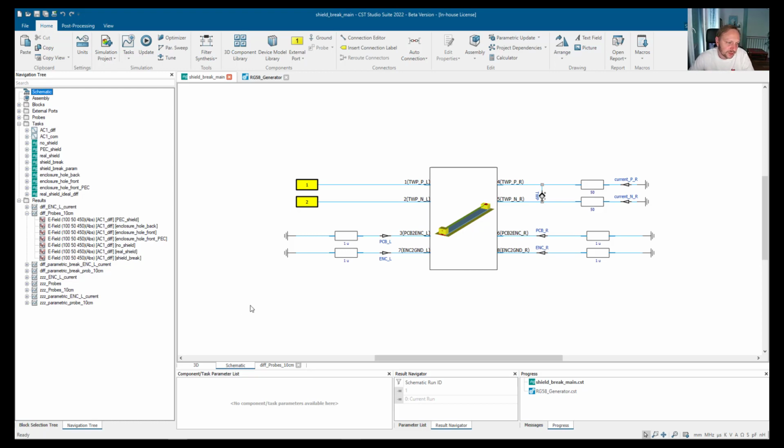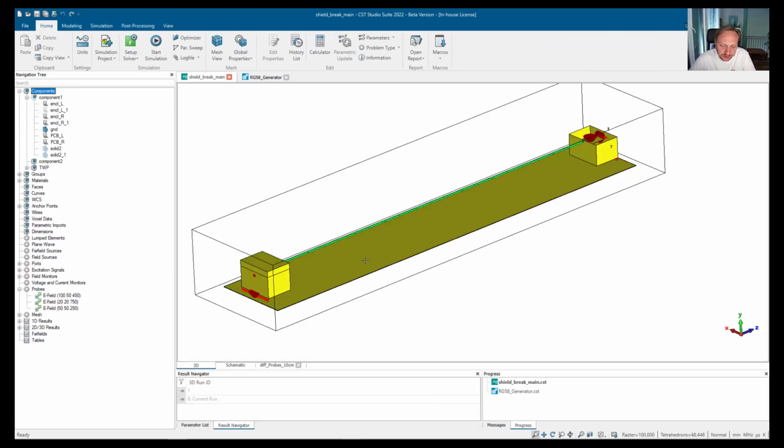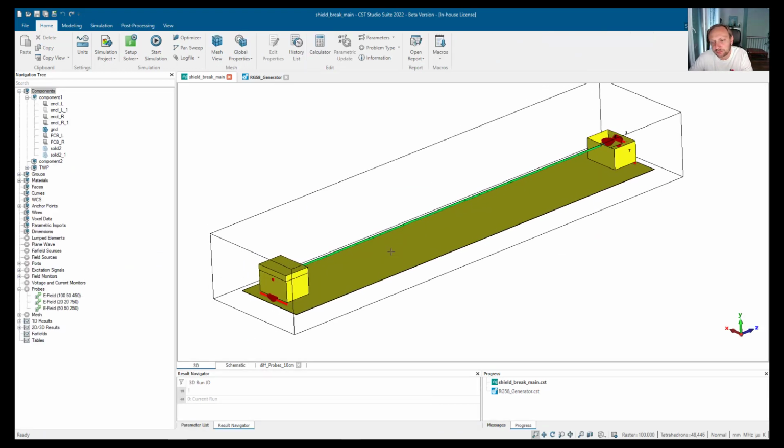These are the connections of this reference plane to the enclosure, and from the enclosure downwards to the big plane. And what I would like to show you basically in cable shielding is that the most important thing is the way, or how the current can get from the inside of the cable to the outside of the cable. This will be one of the main teachings in today's video, because you see it actually has the biggest impact.